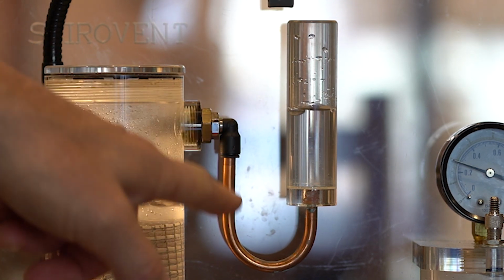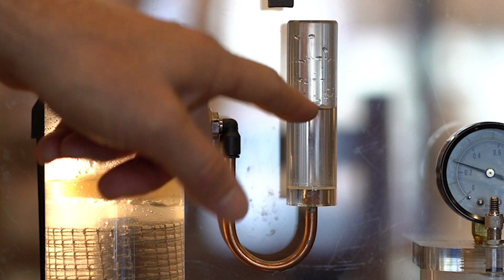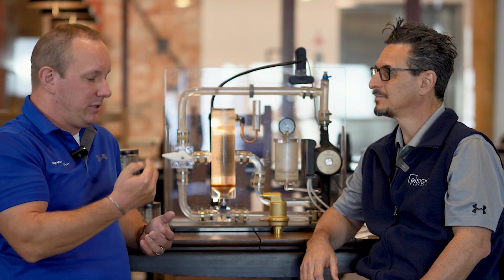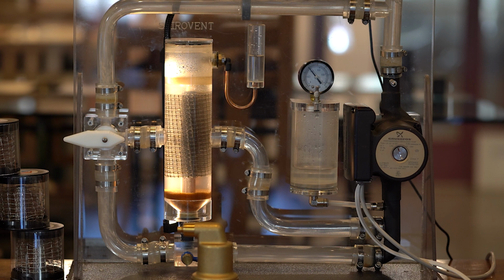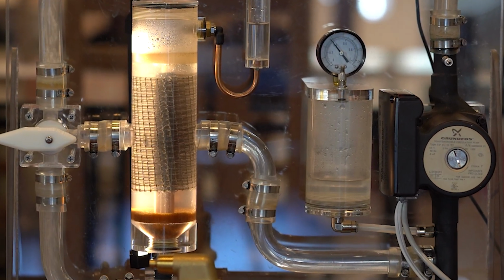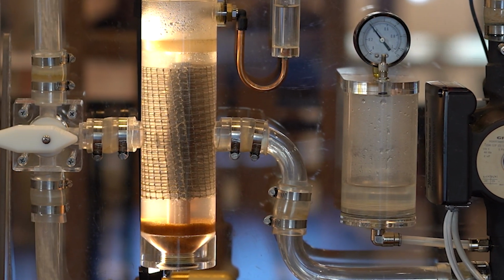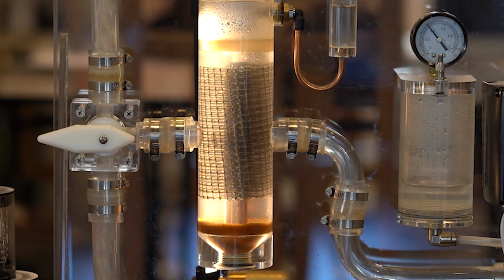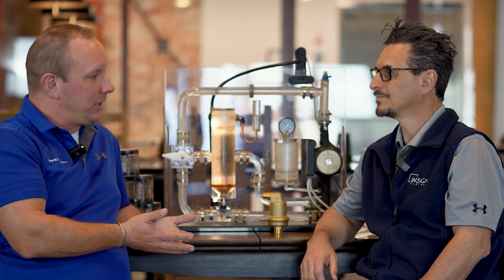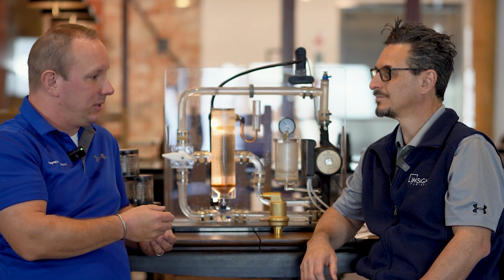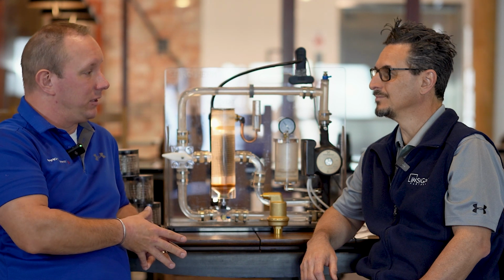I never really put those 2 together, but okay. Yeah, you can hear it going around the bends, and obviously there's a bunch of U-bends everywhere in in-floor heating. It's a weight difference as well. The house was brand new, but you could still hear the floors creaking. So that was a really easy indicator of what entrained air is. For technicians, they can see it with pressure gauges. They bounce all over the place. That's entrained air basically hitting that pressure gauge.